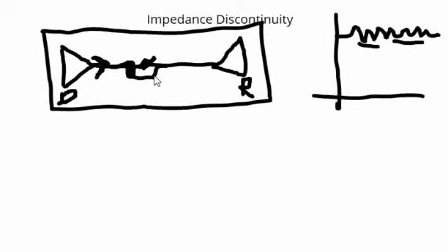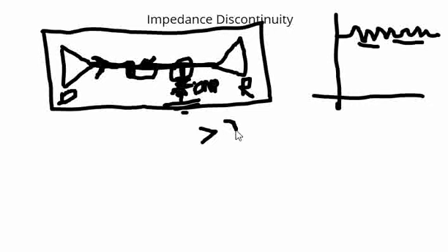So we will talk about vias later. Vias are one of the important elements in a PCB which cause impedance discontinuity. And then let us assume there is a trace like this, and then we have a pull down resistor which is mounted towards the receiver end, and we made this pull down resistor DNP. That means it's not populated. When it is not populated, there will be a line coming in parallel to this, which can be a source of impedance discontinuity if this line is longer than lambda by 4.